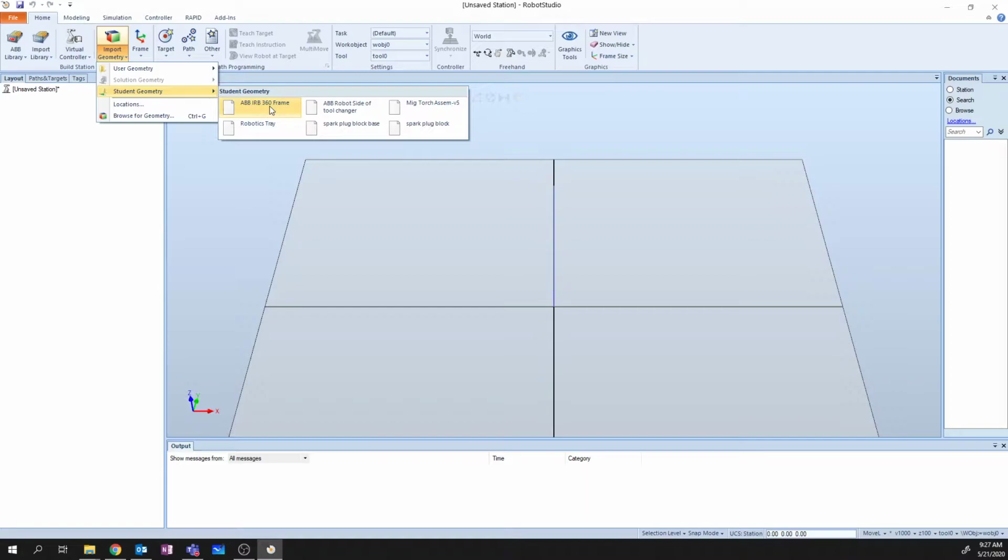Well, in RobotStudio, as you may know from working with robots, the z-axis is vertical. So you need to keep that in mind when creating your object if you want to simplify the import process. We can manipulate these objects around. However, we're not going to be doing that in this video.